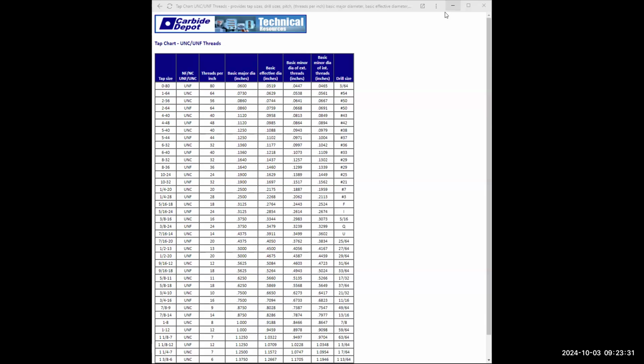This is going to be counterbore space percent C 0.75 DP 0.25. Click. Last time I entered, I should have clicked and then entered now, or hit escape. Doesn't matter. All right, we left one hole.